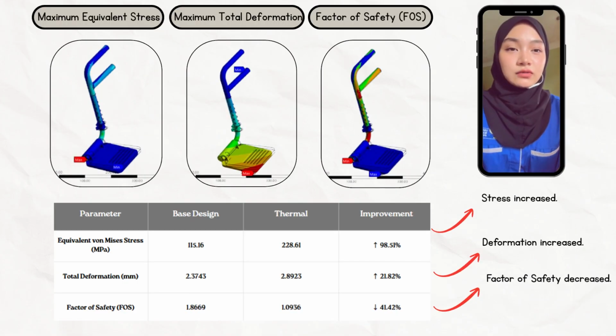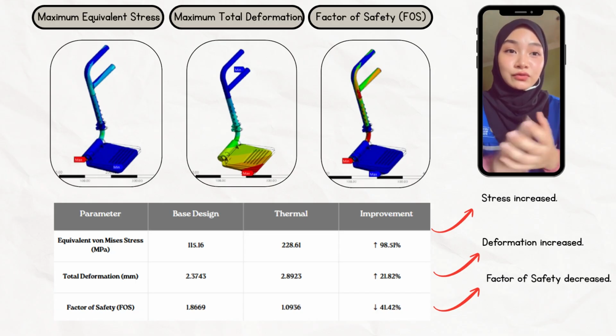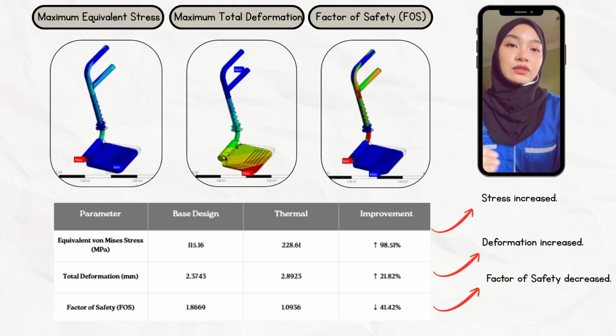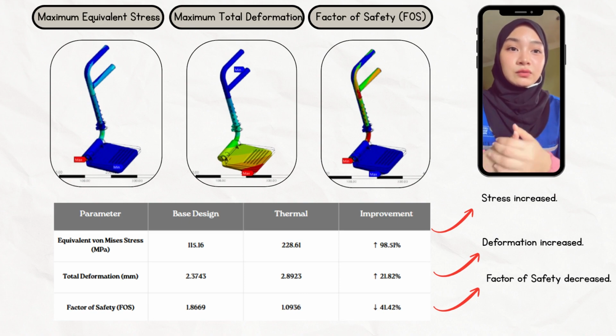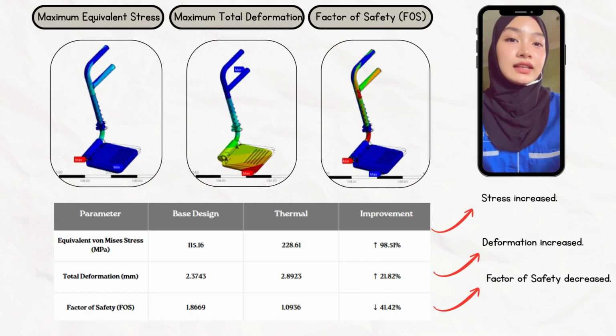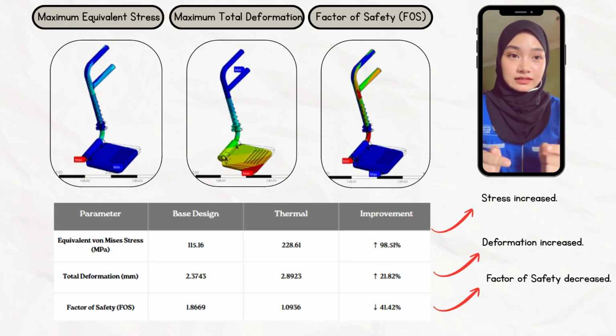From the result, the equivalent stress increased from 115.16 megapascal to 228.61 megapascal, which is an increase of 98.51%. The total deformation also increased from 2.3743 mm to 2.8923 mm or 21.82%. At the same time, the factor of safety decreased from